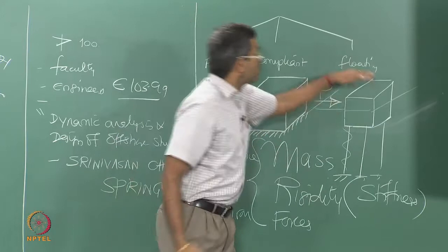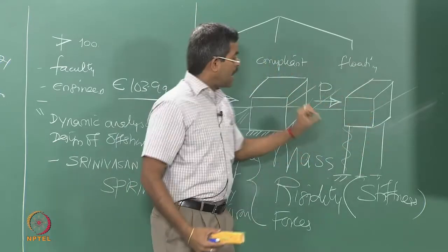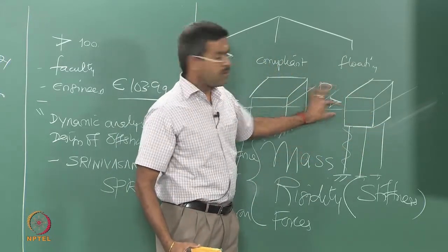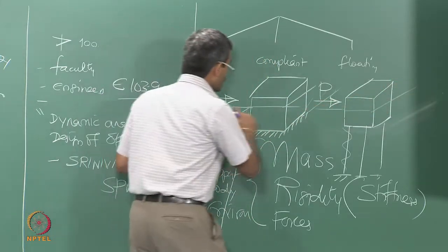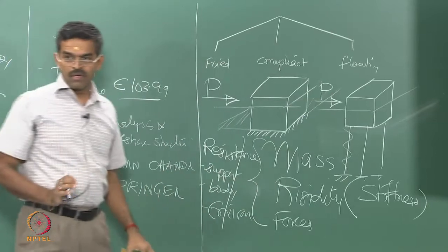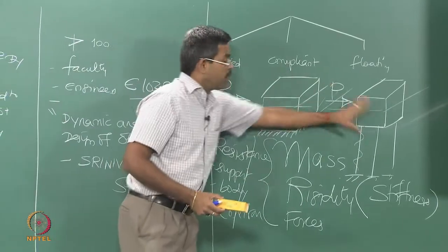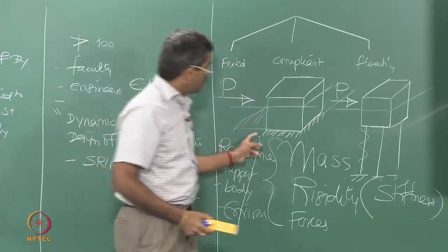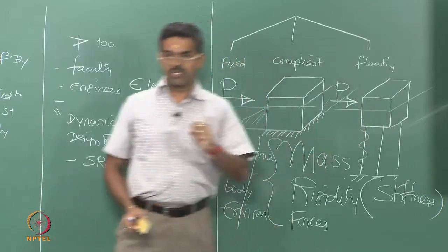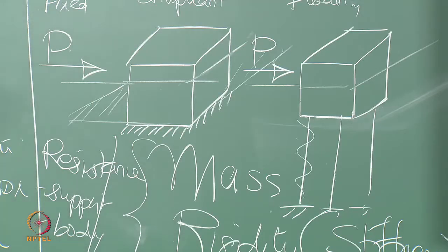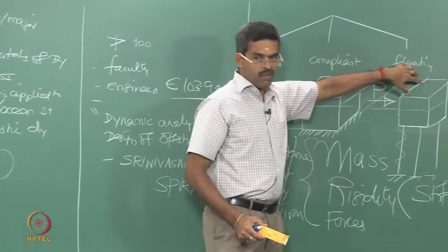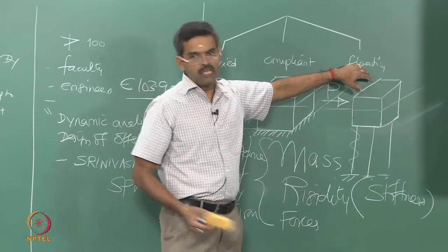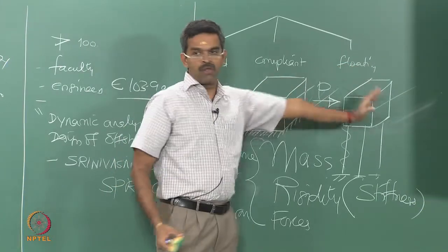When they float, this structure invokes additional force from the free surface, whereas where the structure does not float, more or less the force on the free surface is fixed. So, the additional forces coming on the member depend on the geometric conditions of how the structure is supported. So, if you do not understand this variation between the types of platforms, we will not be able to do dynamic analysis, because we really do not know what forces are coming on the structure.